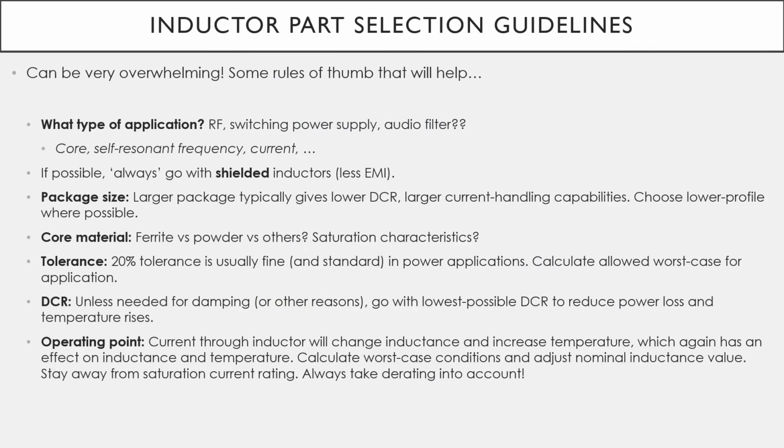Finally, I'd like to leave you with some very generic part selection guidelines for inductors and what you need to watch out for. Of course, this whole thing can be very overwhelming, especially if you've just started out with hardware design, but here are some basic tips. The first thing is, what type of application are you dealing with? Is it RF? Do you have to take care of self-resonant frequencies? Is it to do with switching power supplies, where maybe current and saturation is more of an issue? Or audio filters, where you have to avoid non-linearities, and you're not too worried about current handling or getting close to these self-resonant frequencies? That will determine the type of inductor, type of core, type of properties you will need to choose.